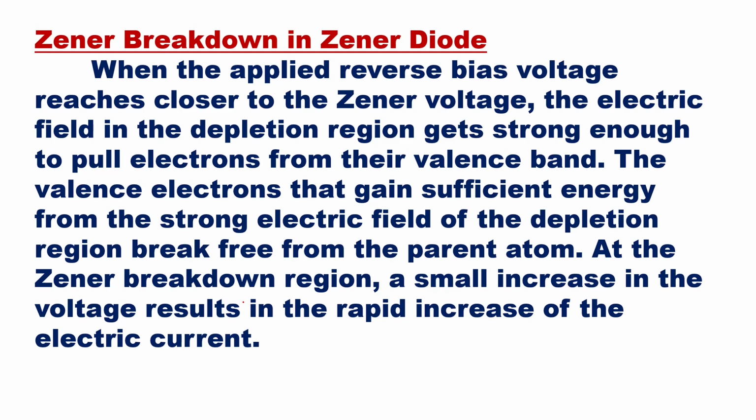Now, this is the concept of Zener breakdown, which takes place in the reverse bias condition. When we draw the graph of the reverse bias condition in the third quadrant, with minus current and minus voltage, there will be a sharp breakdown. The breakdown happens at a voltage which is the Zener voltage. This is your Zener breakdown. Clear? It happens when the voltage remains constant and the current increases.